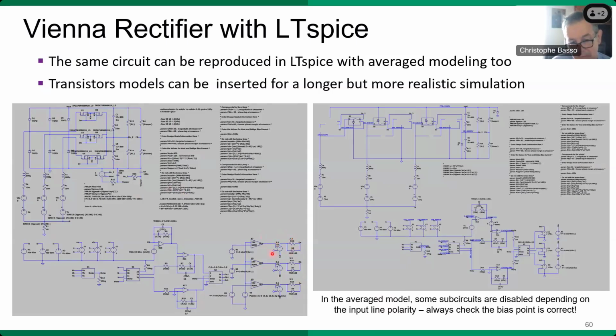It's key for proper simulation to exactly model the driver structure you're going to have for driving this SiC, and not only the on and off voltages, but also all the parasitics you will have in the drive path, like the stray inductances and this kind of thing. And then I also have built the average models. So you can see some of these models here just disappear when you select the time at which you freeze the DC operating point.